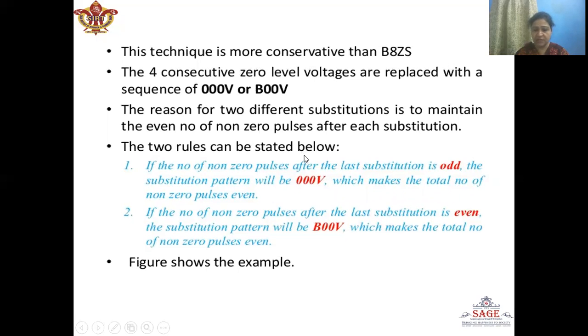If the number of non-zero pulses after the last substitution is odd, the substitution pattern will be 000V, which makes the total number of non-zero pulses even. Whereas if the number of non-zero pulses after the last substitution is even, the pattern will be B00V, which makes the total number of non-zero pulses even. So if the number of non-zero pulses after the last substitution is odd, we will use the pattern 000V. And if it is even, we will use the pattern B00V.